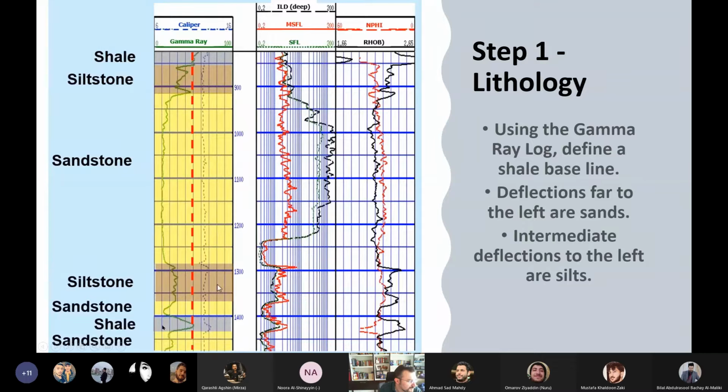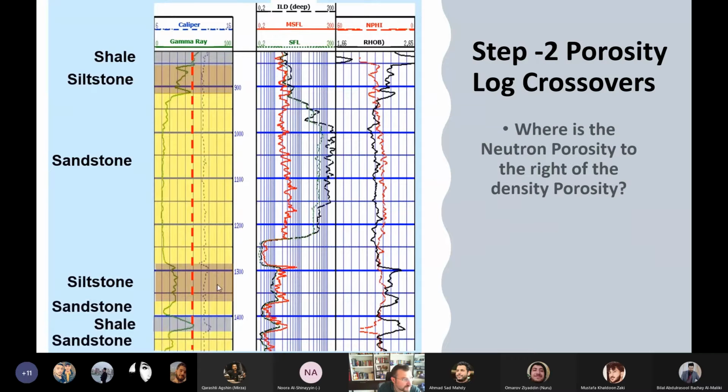Yeah, it's the yellow ones. But the shale, it considers this one as shale actually. If you are at 50 or 60, this has to be siltstone actually. That's something wrongly written in here. So it's like that. Okay, when you reach 90 to 100, you can consider it as shale. Tiny shale structures, maybe they can be tiny shale, but when we were doing this, we already got it as siltstone. Okay, so we understand the idea.